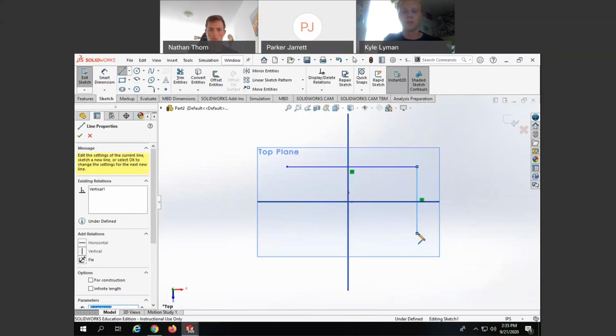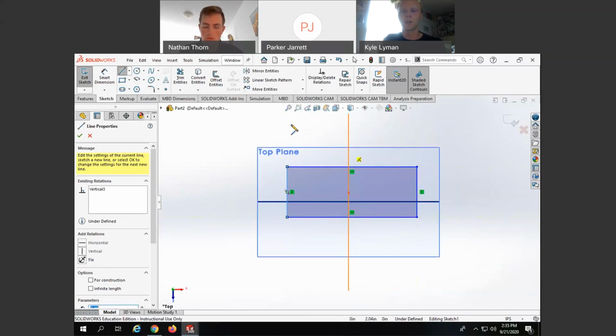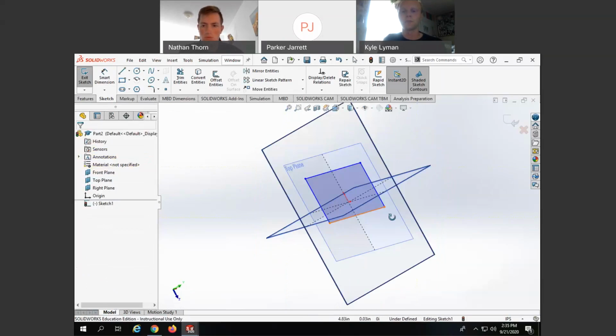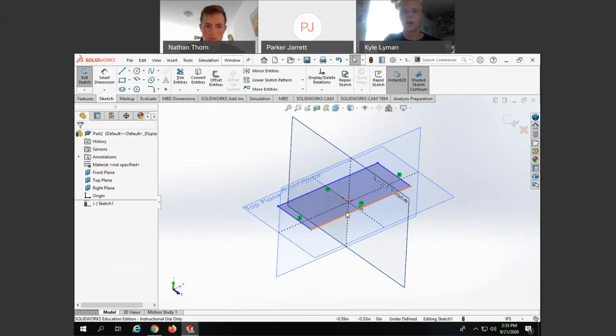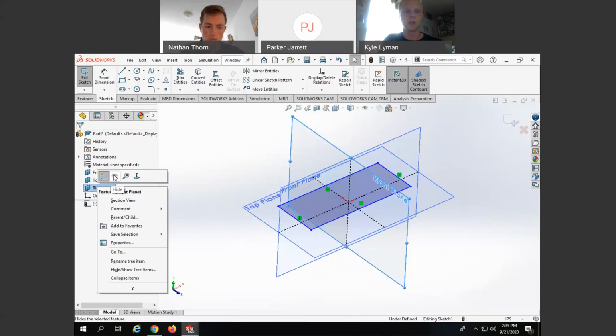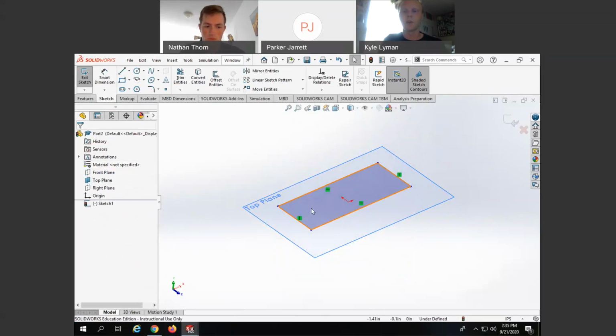Here it'll be 2 inches. Here we're gonna use the simple draw feature where it connects the line automatically, and boom. So it highlights this little blue box. So I just did right click select there to end it. So it highlights this little blue box, which means it's a complete surface. Now I'm gonna hide these planes because at this point I know what I'm drawing. I know where I want to draw it. I don't need these anymore to help me out.